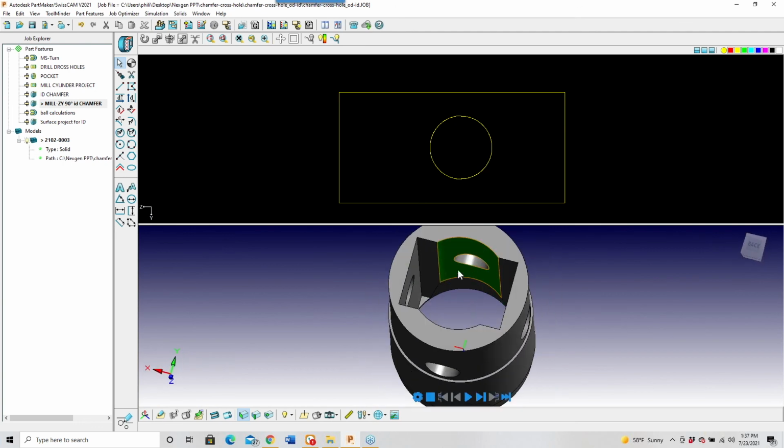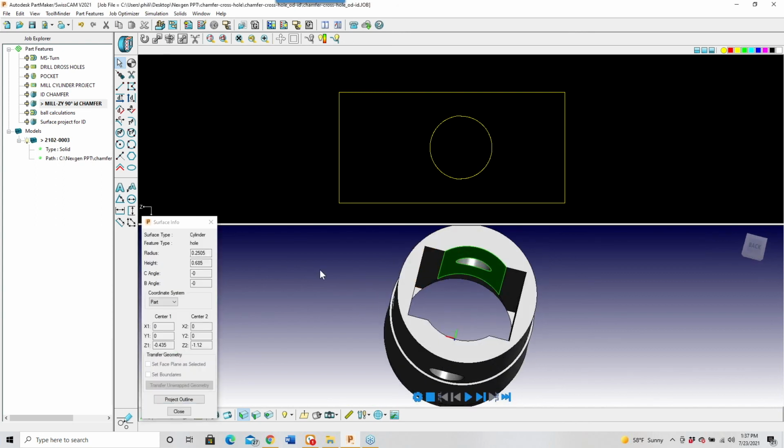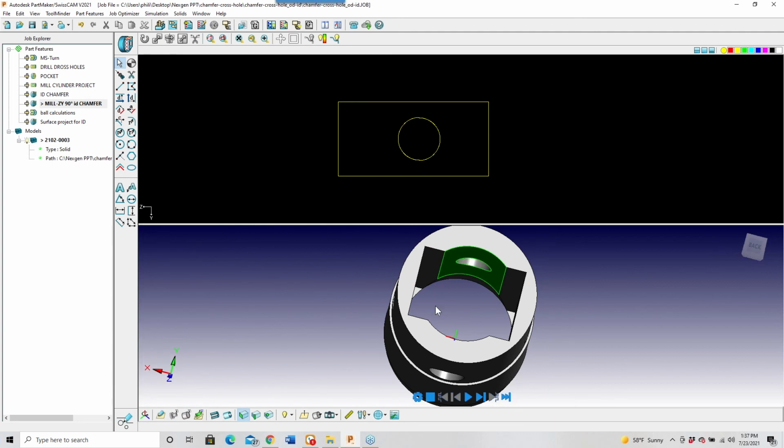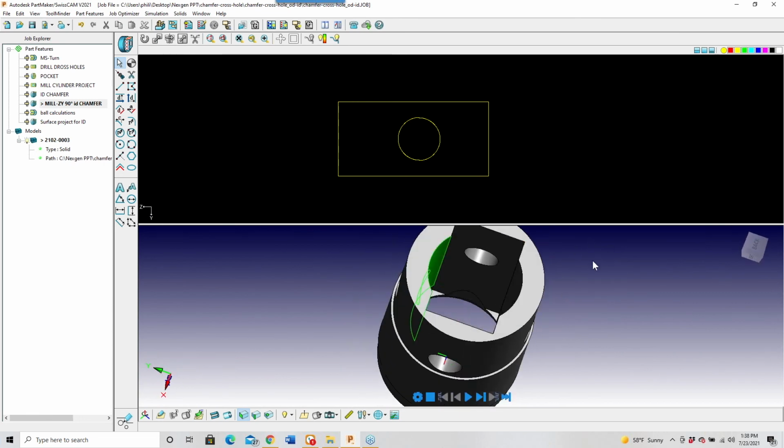So you just have to make sure the dovetail cutter, when it's cutting this, the edge of the cutter itself is not walking itself into this radius here. Okay, I follow you. It'd have to be a real small dovetail cutter for this one. But yes, you can use dovetail cutters for that, especially on the flats. The flats is dirt simple with the dovetail cutter because we don't have to worry about the edge of the cutter running into a radius. We got plenty of space here.